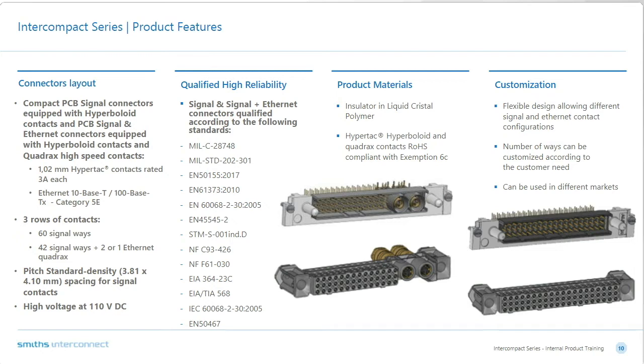The lower mating force, for example the insertion and withdrawal forces, reduces strain and improves serviceability, and particularly gives stable contact resistance. Because remember, all of these things ultimately converge in giving you a stable contact resistance, because from a contact design standpoint, that is what you're trying to achieve.